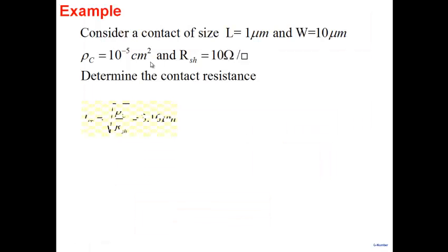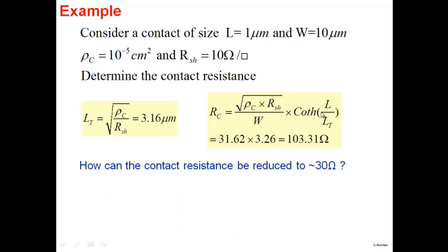And for what reason? Well, two reasons here. One is you can obviously see that as you keep the doping very high under the contact, R sheet goes down. Sheet resistance goes down here. It may become 1 ohm or it may become 0.1 ohm. So this resistance goes down and therefore your overall contact resistance becomes small.